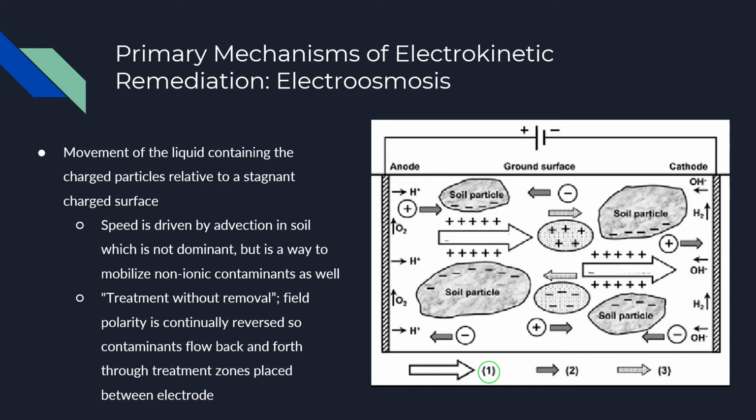When a voltage is applied, this causes the lined-up cations to move extremely fast towards the cathode through the liquid, pulling the bulk fluid along with their movement. This leads to the liquid ultimately moving towards the cathode. While electroosmosis is not as powerful as electromigration of ions to either electrode, it is useful in that this movement can move neutral compounds that would otherwise be left untreated.